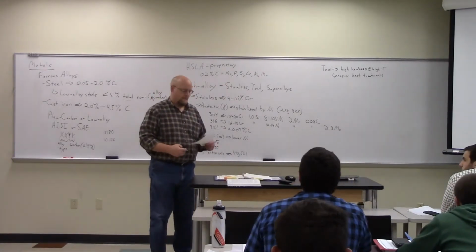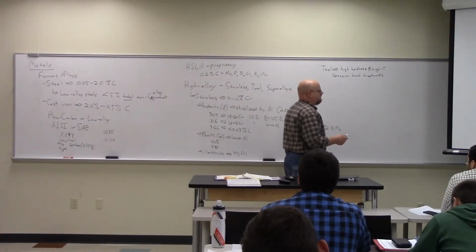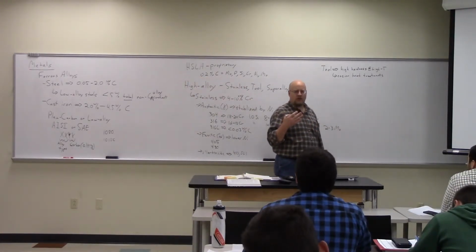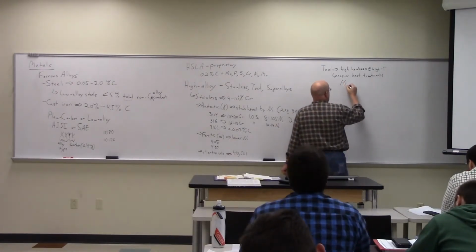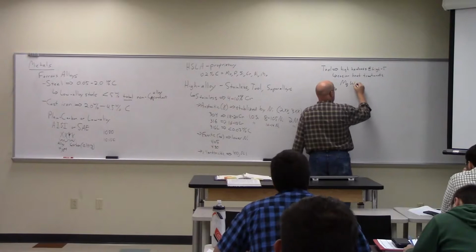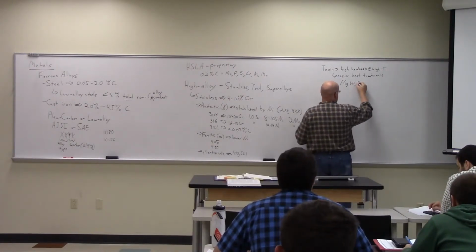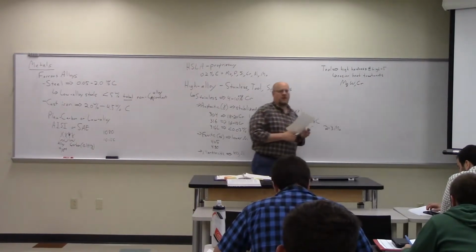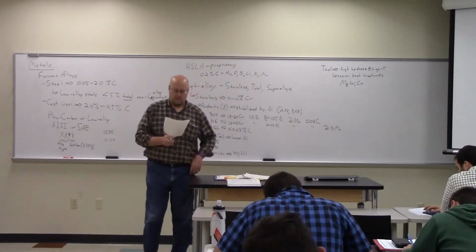Is tool steel as hard at room temperature as at high temperature? Yeah, it's just that it maintains its hardness. I don't know exactly what the relative hardnesses are. But molybdenum, tungsten, and chromium are typically the alloy elements there.